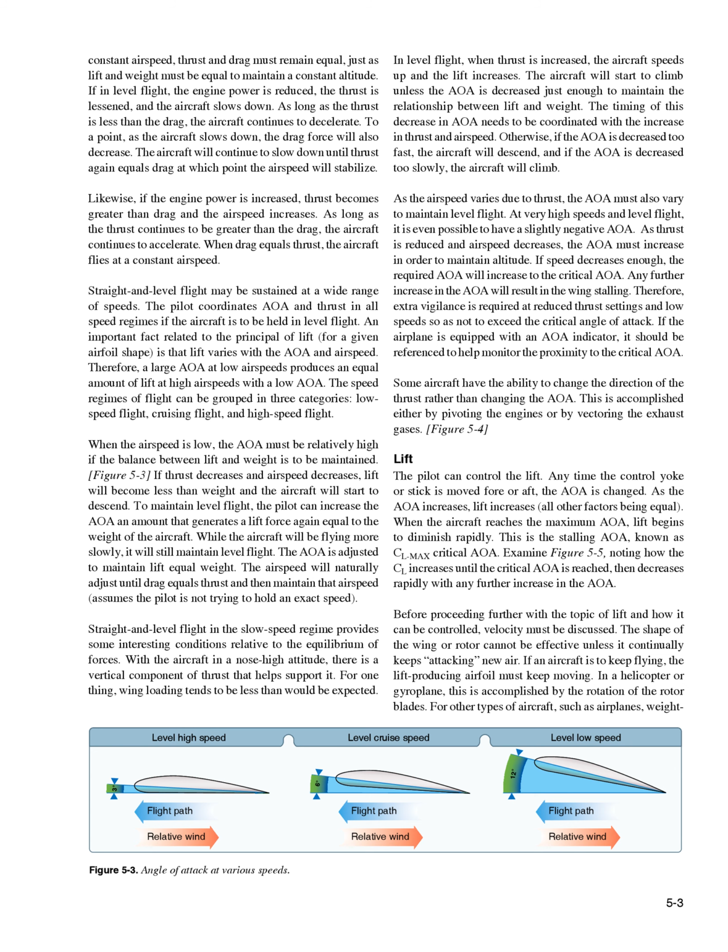Likewise, if the engine power is increased, thrust becomes greater than drag and the airspeed increases. As long as the thrust continues to be greater than the drag, the aircraft continues to accelerate. When drag equals thrust, the aircraft flies at a constant airspeed.